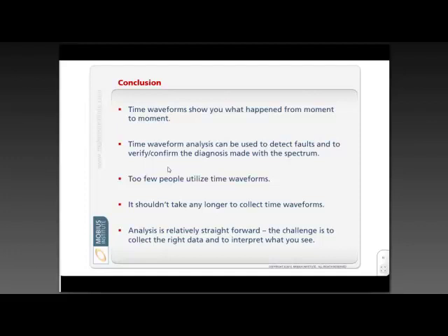The time waveform shows you what happened from moment to moment. As those balls roll around, as those gears mesh together, all those sorts of things, we get to see exactly what's happening. It really gives you a unique perspective. It can clarify what's going on inside the machine where the spectrum may give you inconclusive information.